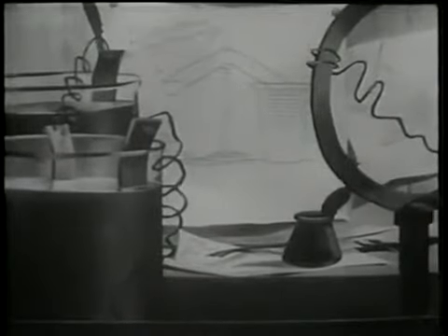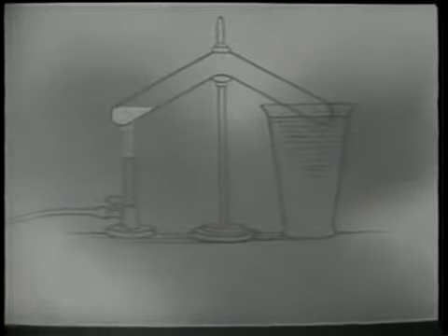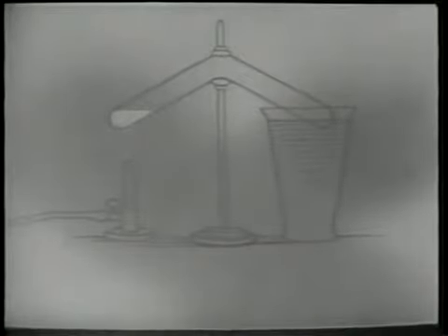The absorption system is based on principles developed in a famous experiment conducted by Michael Faraday. He sealed in a bent test tube a compound of silver chloride, a white powder, and dry ammonia gas which had been absorbed by the powder. He heated the end of the tube containing the powder and at the same time cooled the opposite end of the tube with water. Ammonia vapor was released during application of heat and was condensed in the cool end of the tube.